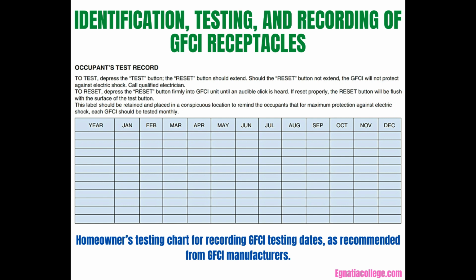Will the homeowner recognize if a receptacle is protected by a GFCI circuit breaker located in an electrical panel far from the actual receptacle? These are important questions and a possible reason why the CEC requires identification, and why the CSA requires detailed installation and testing instructions to be included in the packaging for the GFCI receptacle or circuit breaker.